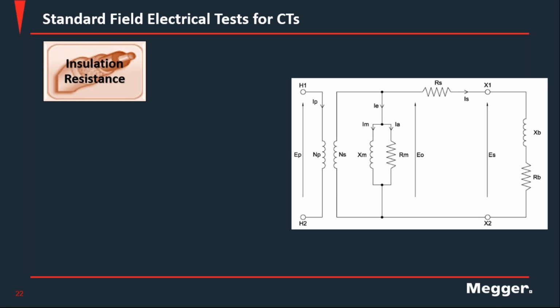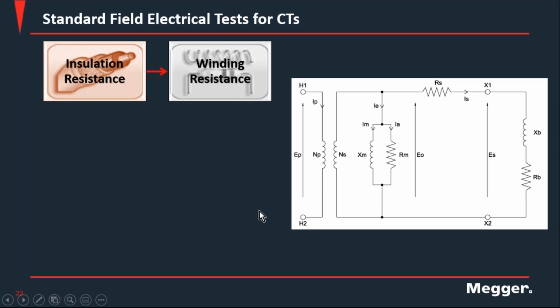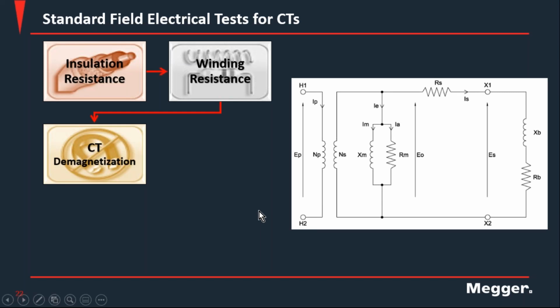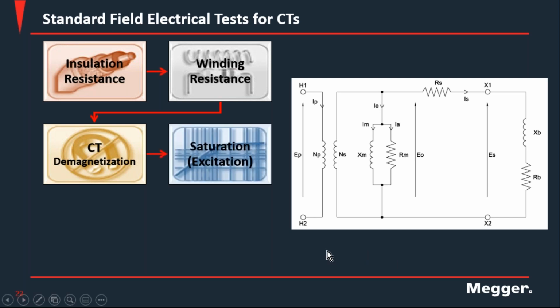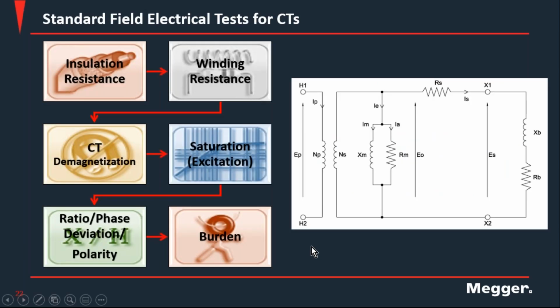So if Bonnie can help me show that slide where we describe the recommended sequence of measurements, you notice that the first two measurements are insulation and winding resistance, both DC based, when one is applying your DC voltage and the other is injecting a direct current for winding resistance. And then you notice that the next phase in the test is demagnetization, right?